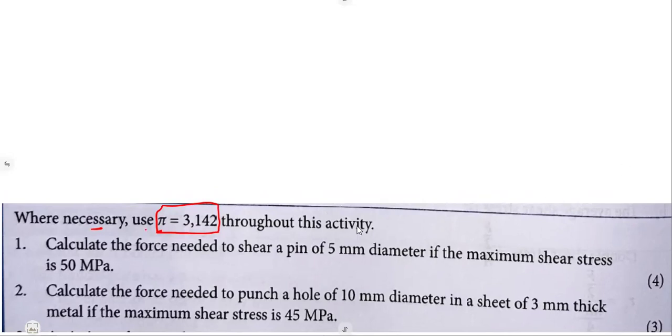All right. Anyways, number one, we are given: calculate the force needed to shear a pin. To shear, meaning there is a shear force, which causes a shear stress of 50 megapascal.